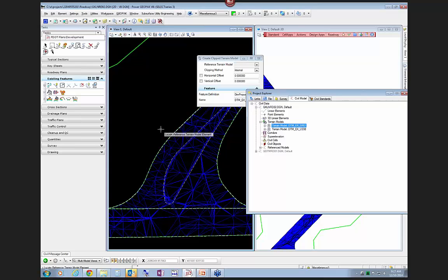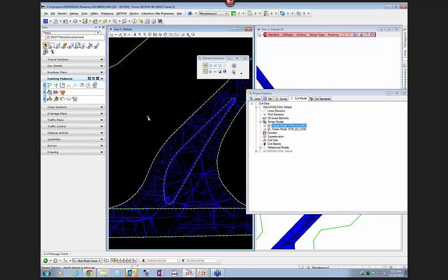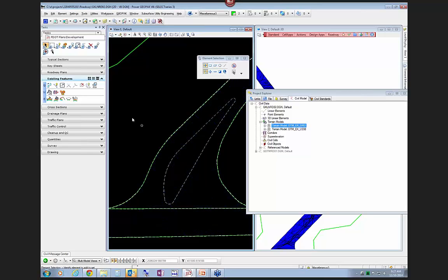Over here, I'm going to locate the terrain, which is this one, and then I'm going to locate the clipping element, which would be this one and this one. And maybe because it's not a complete shape, which I might have to do. And then, that's exactly what it is. I forgot one step, so let me turn that off. I need to make shape boundaries of those.